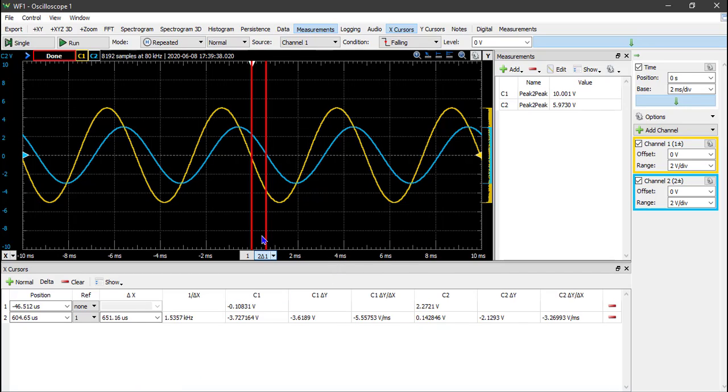Now, just something to note is that what you should see as you keep doing each of the different frequencies is that as you increase the frequency of the input, the amplitude of the output wave continues to decrease, and the time delay also continues to decrease. Now, that might be counterintuitive, because the phase shift in degrees, as you should have found in your pre-lab, increases as you increase the frequency.